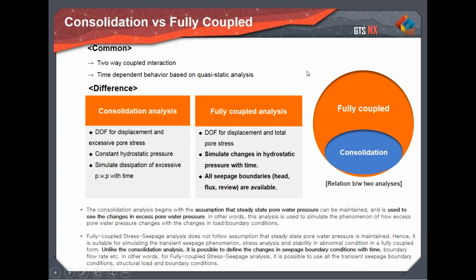And the other comparison that will be the main focus today is the fully coupled versus consolidation. So they actually have some similarities and then some key differences. The similarities are that for both cases, you can consider the stress and the seepage conditions in the same stage, and they're both time dependent. However, the main differences are in some of the initial assumptions and some of the boundary conditions you can use.